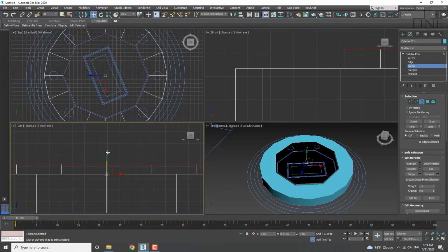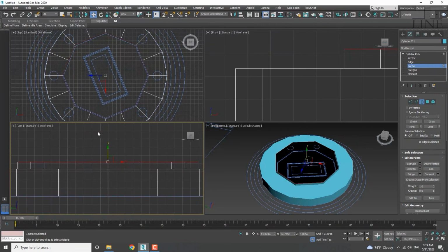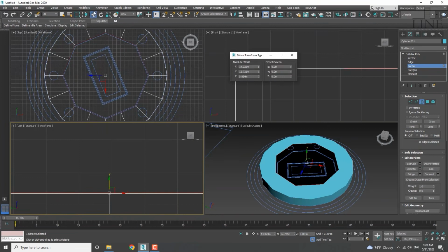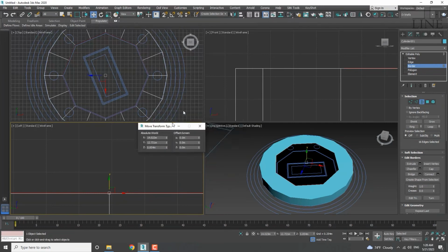It might be difficult because it doesn't move the numbers up and down very precisely. Okay. I'll press Shift again, but the number is too much for me. I'll bring it down close to the point, and this time I'll right-click on the W section or on Rotate or Scale, and this window will be displayed so that you can enter the exact number.